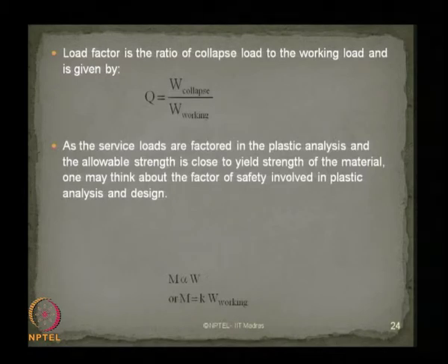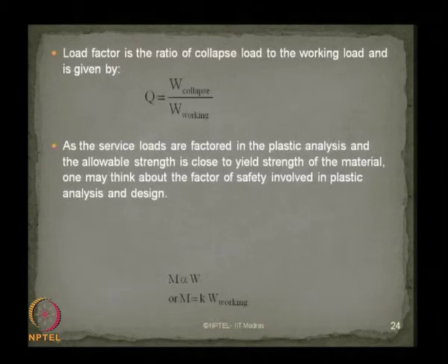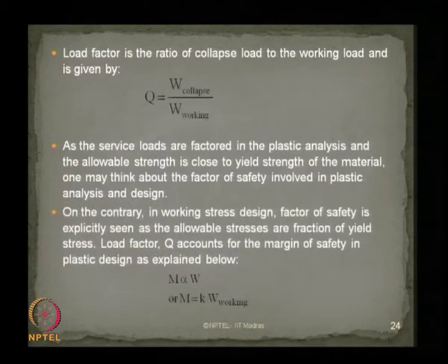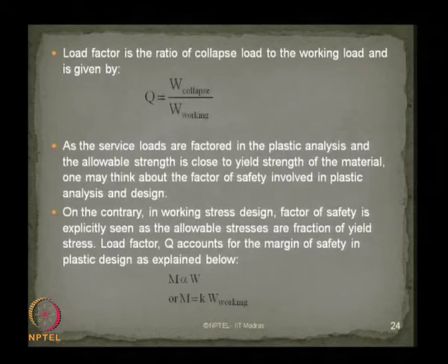Ladies and gentlemen, very importantly, please understand that the service loads are increased by a factor, whereas the allowable strength of the material is closer to the yield strength of the material. Now one may wonder, is there really any factor of safety involved in plastic design methodology? On the contrary, in the working stress design, the factor of safety is explicitly seen because the factor of safety is nothing but the allowable stress as a fraction of yield stress. So only a fraction of yield stress is recommended as an allowable stress. Therefore, you explicitly see the factor of safety in working stress design.